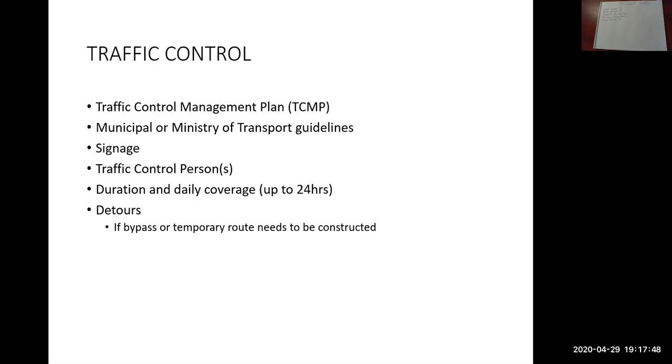If you're in a city like the City of Burnaby, for example, maybe there are existing streets that you can use for a detour. So you don't have to build the detour, you would just have to put signs up to show where the detour is for the public, so they know how to get around the road closure. So again, maybe you need 24 detour signs. So again, there's a cost to that. So know how you're going to build your project. If you're going to close roads, close lanes, detour traffic, what your hours per shift will be, all of that is important for traffic management.